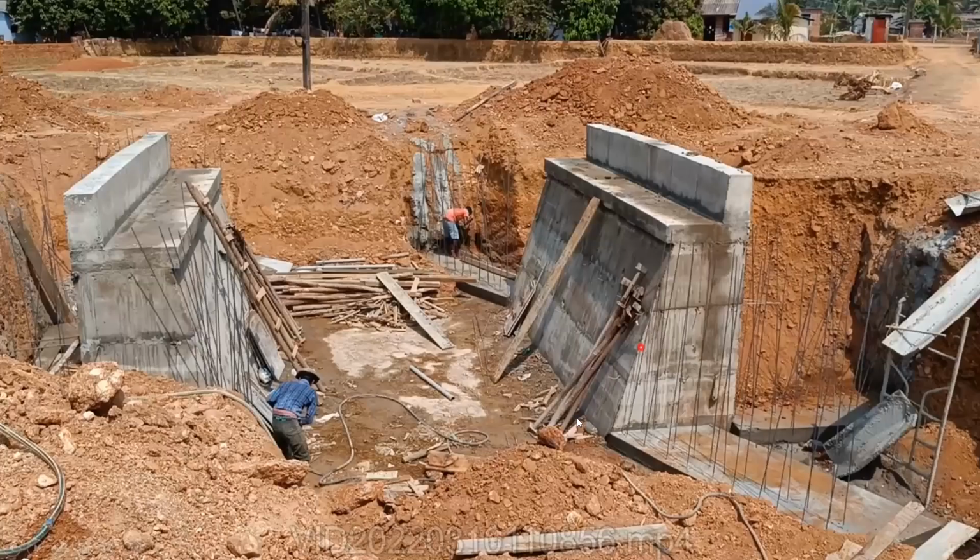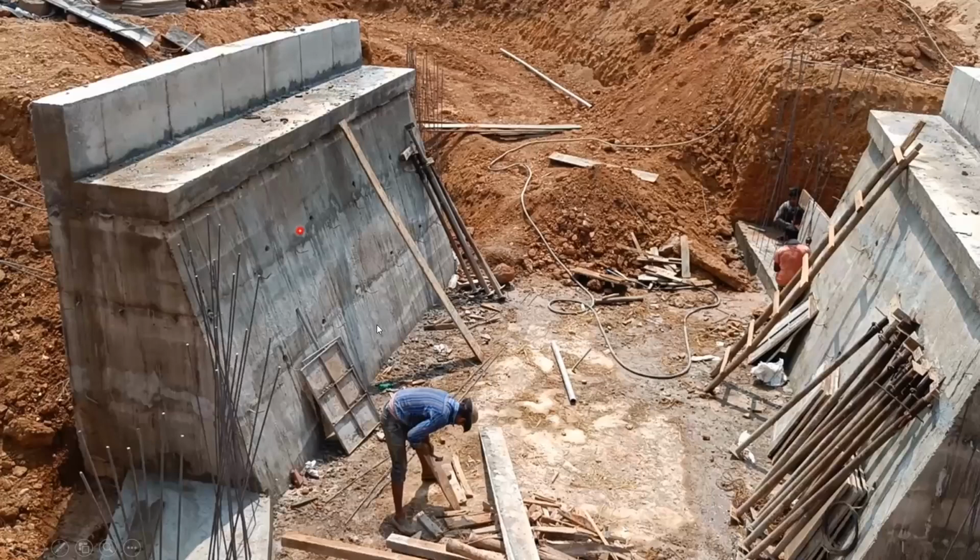Okay, got it? Yeah. So then we are going to make the side retaining walls and all, so that when we do the backfilling, the soil should not come, and also this will give a smooth movement to the flow of the water. If you don't do that, then what will happen? The water whichever comes, it will go in this direction and all. So in order to have a proper way for the water to flow, we create this wing wall here, here, and even in this direction, and this direction, all the 4 directions.